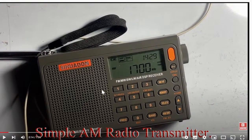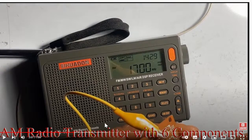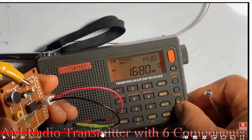Alright, so this is an AM radio transmitter without a coil. Normally in many of our transmitters we used to include tank circuits, which is made up of a coil and a capacitor in parallel. But in this circuit, as you can see, we just have a 555 timer and a capacitor. This one is a variable capacitor, the yellow colored one.